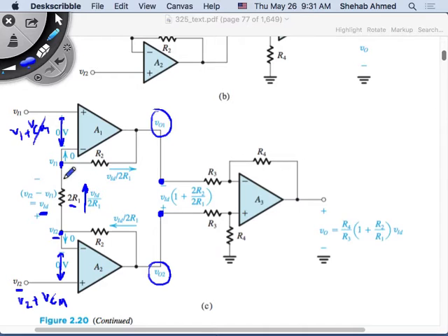Why would you subtract? Because the voltage difference across this resistor is this voltage minus this voltage. If you want to calculate the current, it's this voltage minus this voltage. So now across this resistor, I have my signal V2 minus V1, my differential signal, and I lost all the common mode signal across this resistor. I want to see if I'm able to transfer this nice clean signal, without the common mode signal, to my amplifier without amplifying the common mode signal.